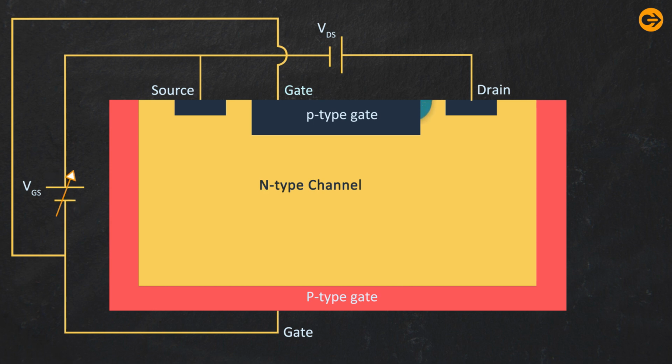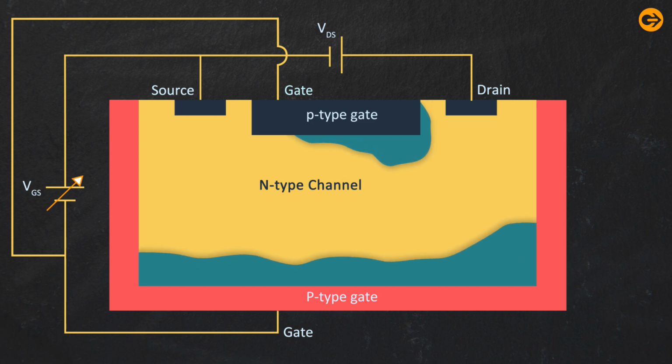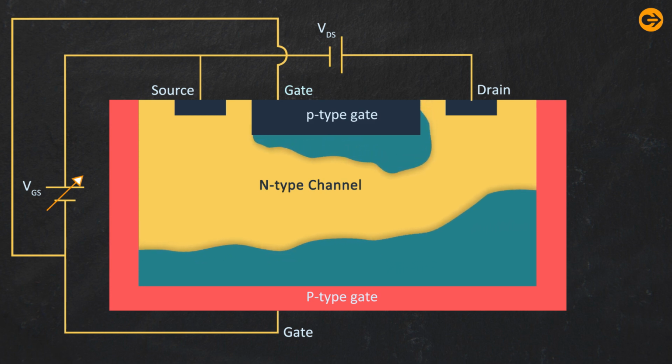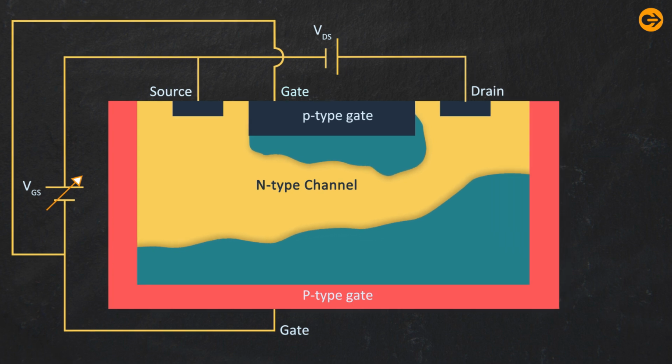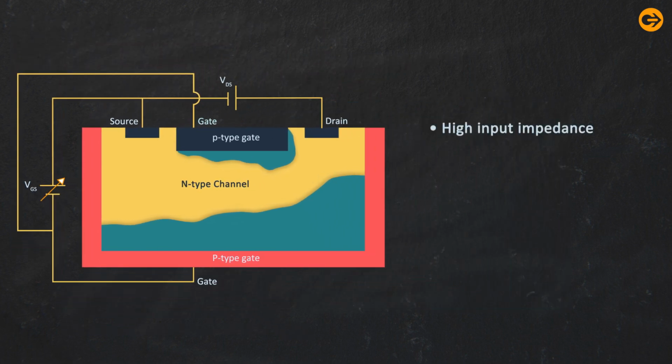Electric field is generated in JFET to control the flow of current in the channel. So the device is said to be voltage operated and it has high input impedance. And current is generated due to a single carrier, hence JFET is less noisy. This is a distinct advantage over the bipolar transistor, which is current operated. So it has much lower input impedance and two types of carrier are also present in it. So it has greater noise.